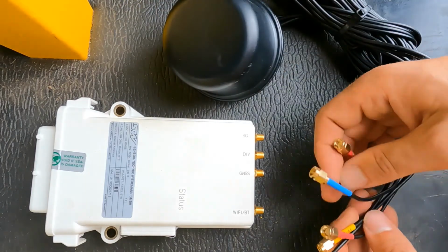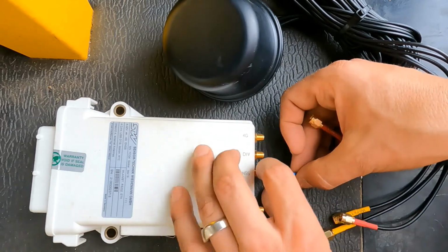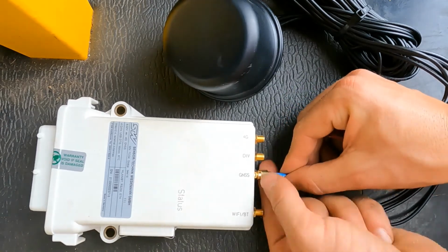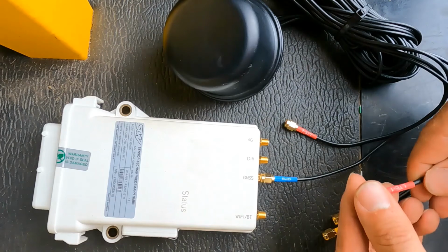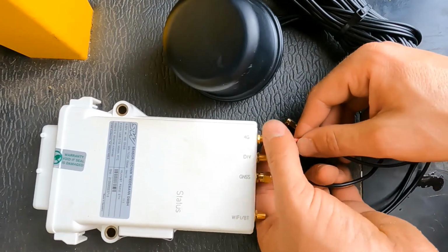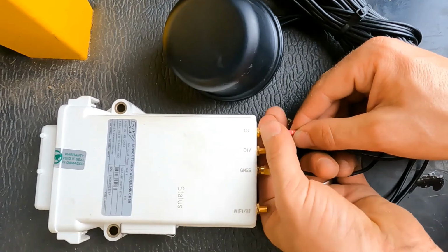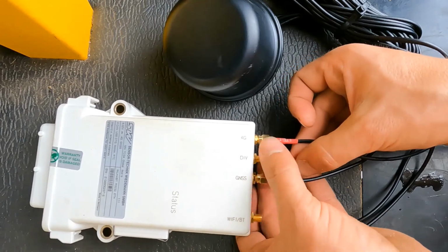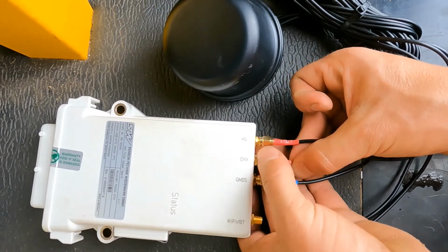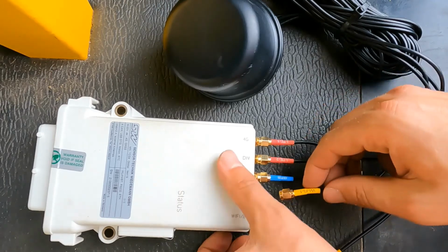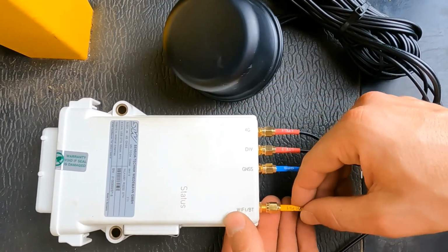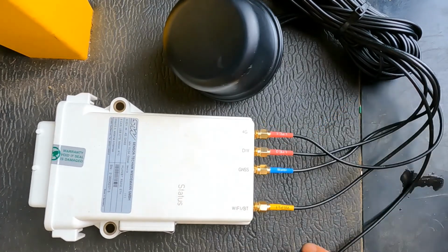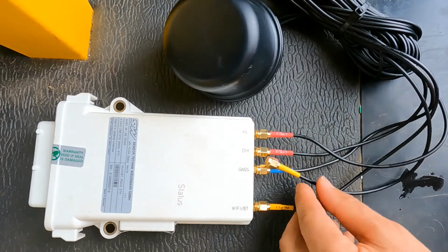So let's go ahead and wire up the dual antenna. The blue GPS is going to go to the GNSS port here. You'll want to make sure that these connections are finger tight, but not too tight. There we go. LTE1 is going to go directly to the 4G port. Here again, finger tight. Same thing here with LTE2 into the diversity port. And this really gives us dual band 4G capabilities by having the dual antenna. And last but not least, the Wi-Fi port. Wi-Fi and Bluetooth combined in the same wire. And Wi-Fi 2 is not used in this installation.